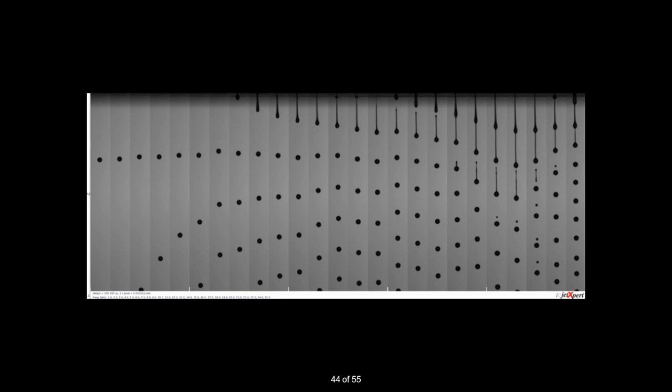So this is a good example of what resonance looks like inside a printhead. As the ink is moving back and forth, being jetted, being refilled, there are some residual acoustic waves going on inside the head. And if we get our frequency just right, which is what's going on here, the waves are building upon each other with every single drop, and we're hitting some sort of resonance frequency. So if you're seeing something like this occur, where the print doesn't look good at certain speeds, but looks good at all the others, it could be something like this that's going on.